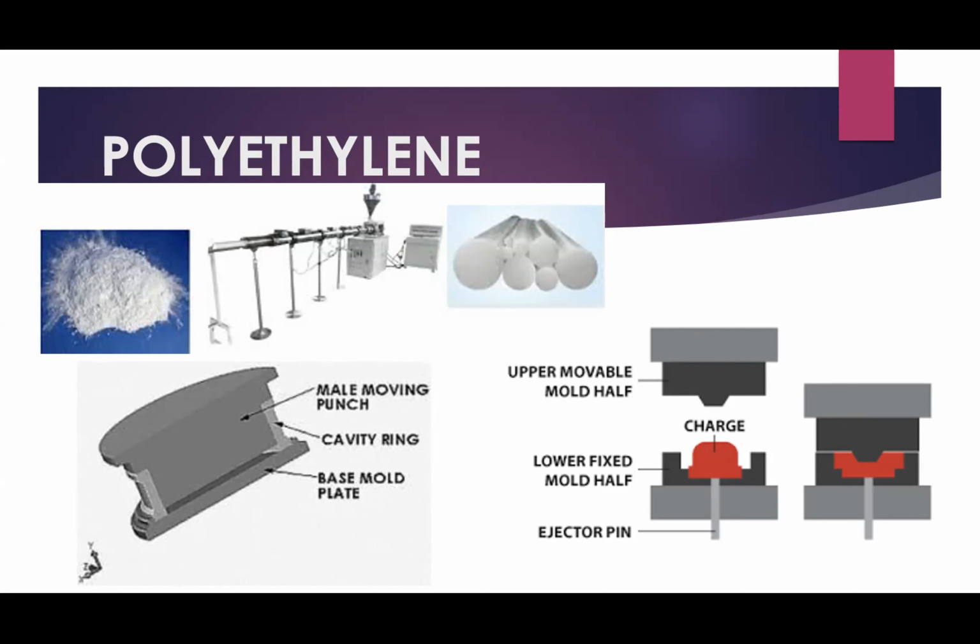Stage 4 is heating, where you want to get rid of some of these free radicals. So you can either melt the poly down, gets rid of all the free radicals, but makes it more brittle, or you can basically heat it to just below its melting point, which gets rid of some of the free radicals, but maintains the biomechanical properties, known as annealing. And finally, you've got packaging. So you've got to make sure you don't package it past its sell-by date.